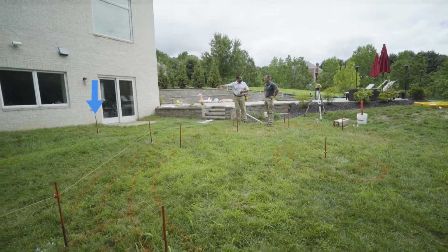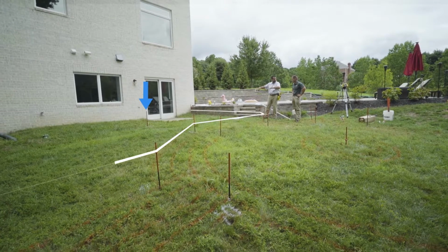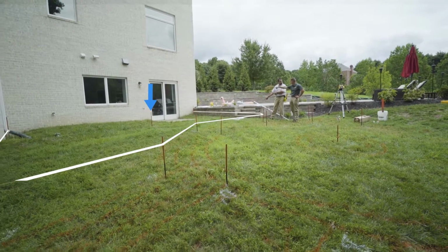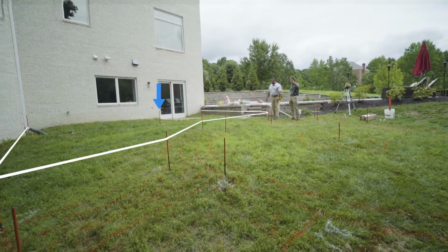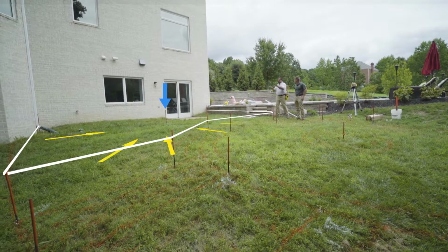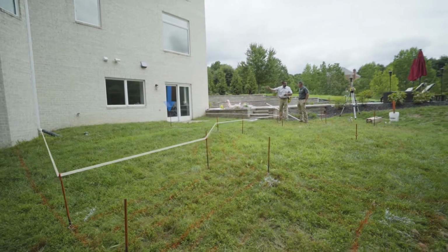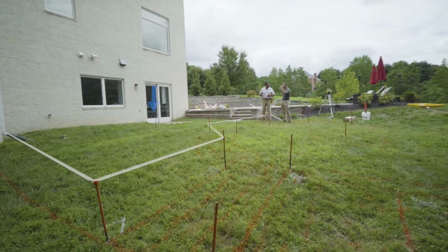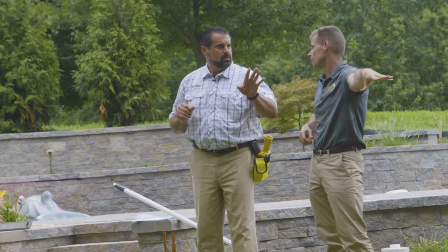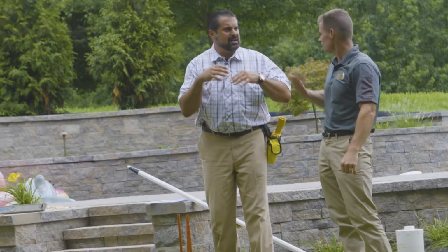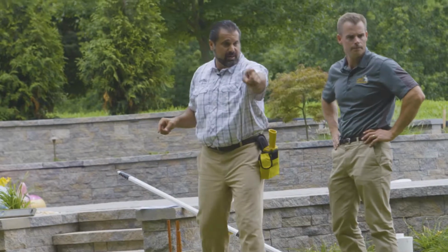There's our drain, right? So we're going to pitch this entire area level on the perimeters, right? Because we have this here. And we have the threshold of the basement over there. We have the steps coming off of our new deck and porch. So we're going to pitch everything into that drain. Run down with what type of pipe? We're going to use SDR35, and we're going to transition all of these tie-ins from a 4-inch to a 6-inch before it goes out to a gabion basket. So we minimize just kind of a riprap area. It's Class B erosion riprap. That's perfect.